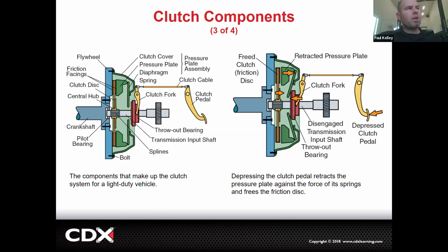Sometimes what we'll get is this bearing just gets chock full of clutch dust, and it may kind of squeak. So if you're fully released, a lot of times this bearing may not make noise. And then when you slightly push the pedal, it might start to squeak. That's getting the bearing moving. Just slight movements of the pedal. All that's changing is the release bearing, the throwout bearing.